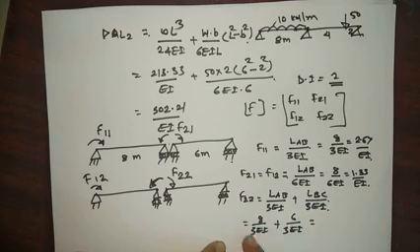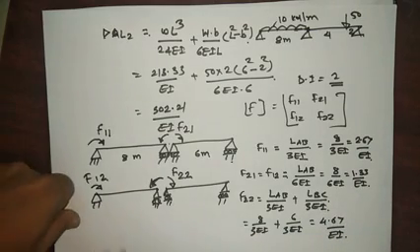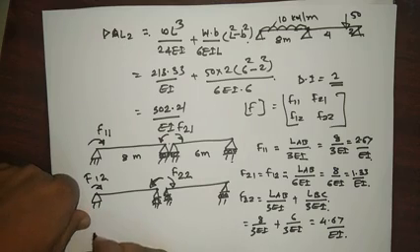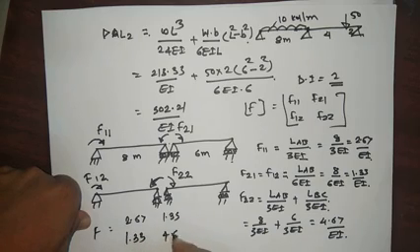So this becomes 2.67 and this is 2. So 4.67 divided by EI. So we got this matrix, that is the F matrix, that is 2.67, 1.33, 1.33 and 4.67.